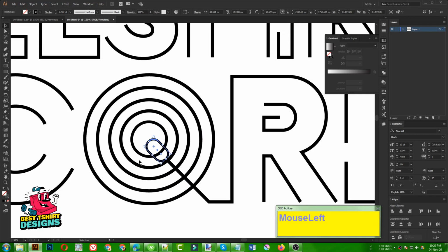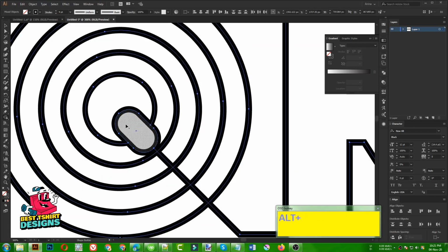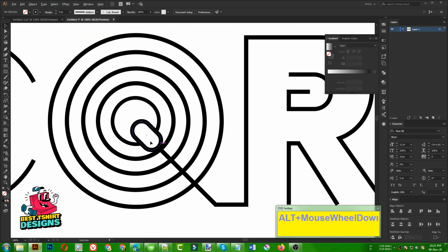So if I select this ellipse and the rectangle, then take my eyedropper and click here, it will be the same stroke as that option here. I first need to select these two parts, and I want this part to look like a cutout effect. I can simply keep it as it is, or I can select them like this, then press Shift M for Shape Builder, and if I click here I can erase that part. These areas are looking good for me, so no problem.